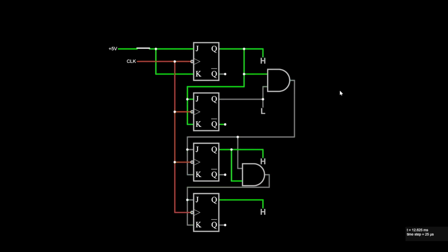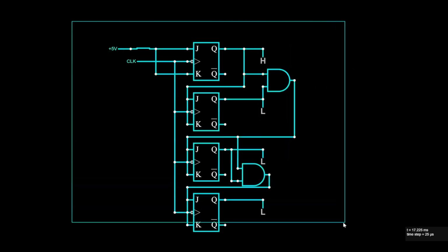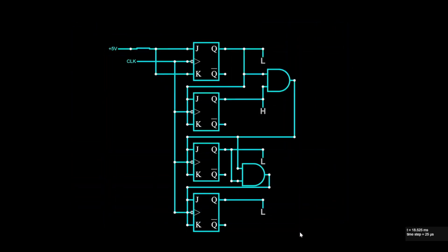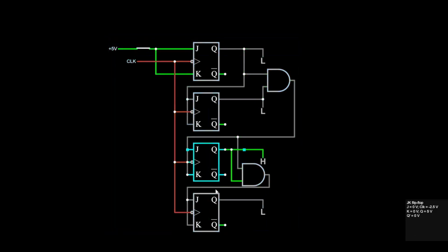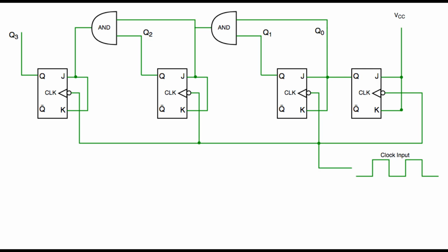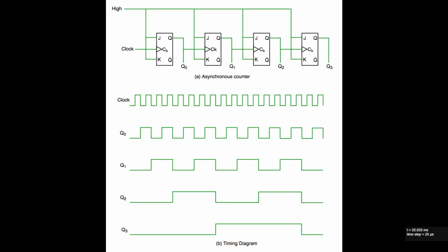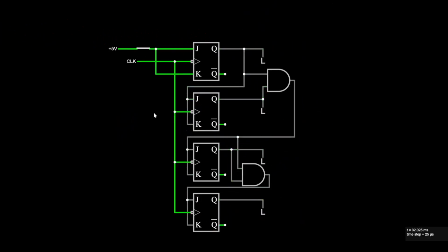And so this is basically what a counter is. That's what the circuit is. The big reveal, it's a counter, right? So our counter here just counts every time our clock frequency pulses. And this is an example of a synchronous counter because all the JK flip-flops are driven simultaneously in parallel. An asynchronous counter, I'll throw it on the screen here. Boom, look at that. The clocks are driven not simultaneously, but based off of the output of the previous flip-flop. And so yeah, that's basically it.